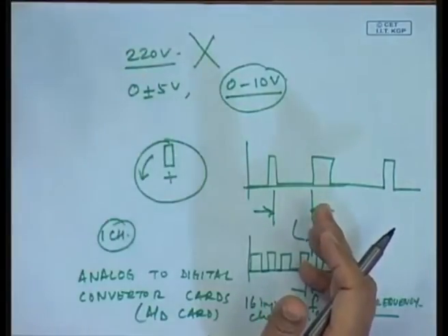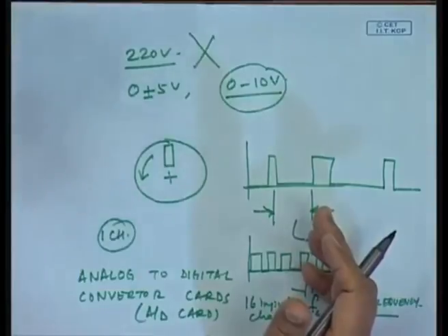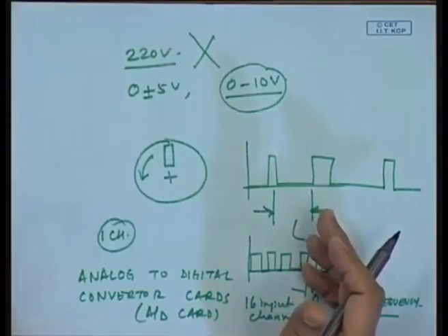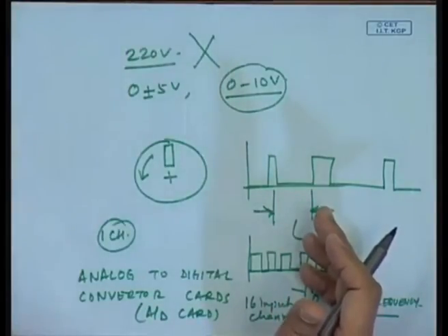And then from the external world, you can plug in wires which are carrying the analog signals into the A to D card, and after the conversion the digital data will go into the computer bus, and then the computer memory devices will have access to that, and the control CPU will have access to such data.